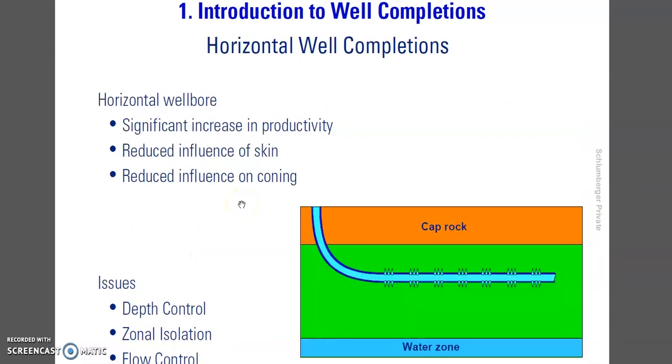Okay, so here we have finally the horizontal wells, and I've already talked about horizontal wells and why we should drill a horizontal well. If we have water zone and gas cap here, the contact area between the wellbore and the formation will be higher than if we drill the well vertically.